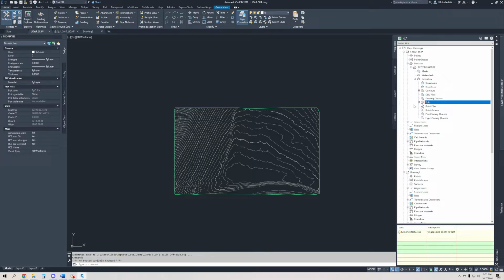And those point files will be loaded in to your drawing and used to create your surface. Point groups, when they bring in those points, they can group them together to, let's say, group it in curbs and asphalt and, let's say, planter boxes and utilities, and they group all those together so they can just import the utilities or just import the curbs.